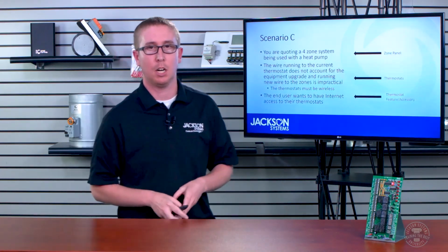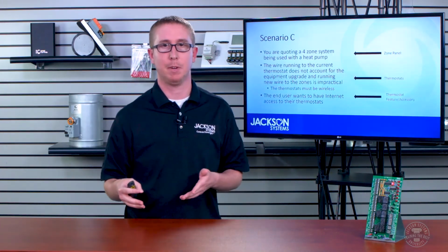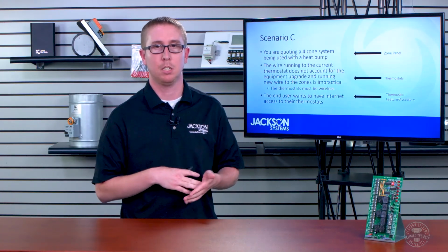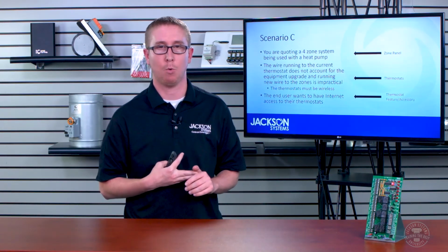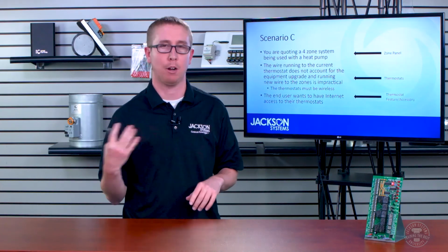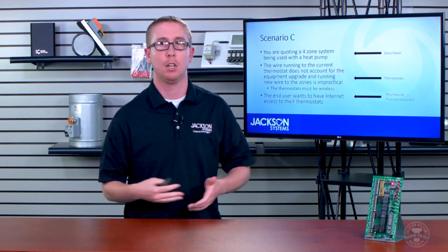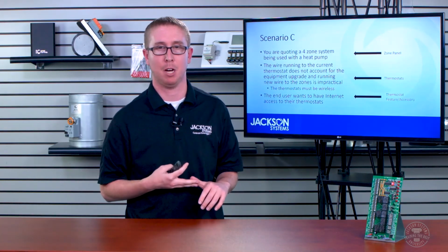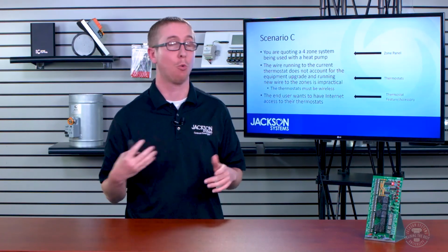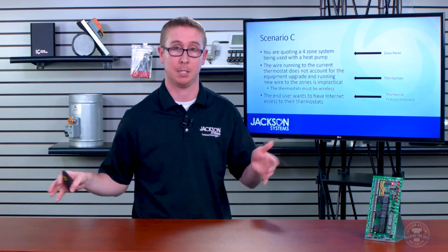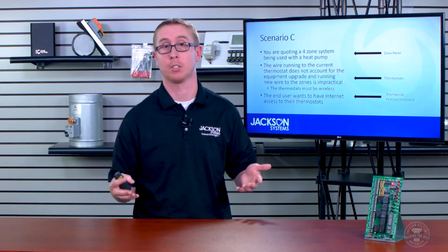Scenario C. So they want a 4-zone system, and it's going to be on a heat pump. The wire running to the current system did not account for the heat pump upgrade. So new wire getting to those zone thermostats would be super difficult or impractical, or maybe impossible. Regardless, you're choosing wireless thermostats to be the best solution, and you need a wireless thermostat in all 4 zones.